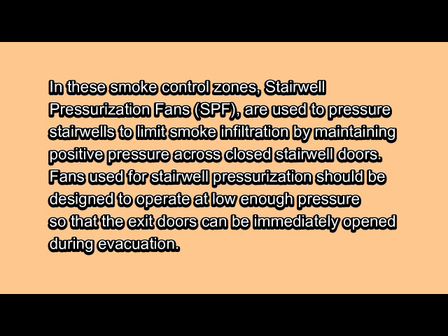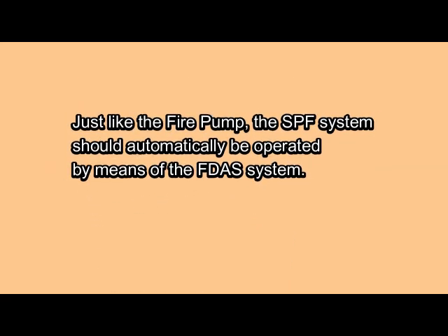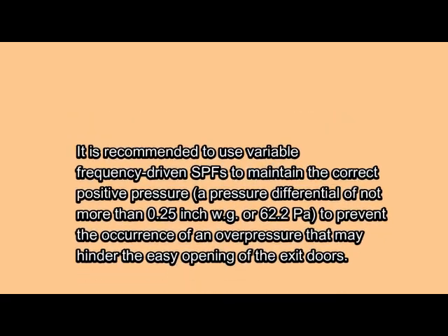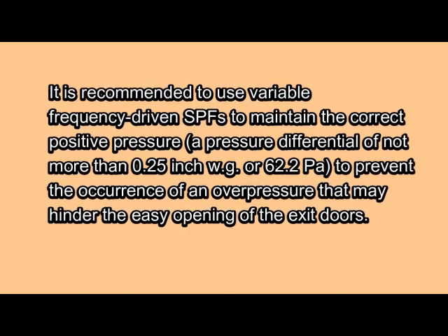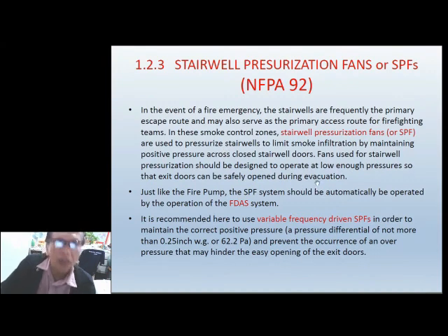Fans used for stairwell pressurization should be designed to operate at low enough pressure so that the exit doors can be immediately opened during evacuation. Just like the fire pump, the SPF system should automatically be operated by means of the FDAS system. It is recommended to use variable frequency-driven SPFs to maintain the correct positive pressure, a pressure differential of not more than 0.25 inch Wg or 62.2 pascals, to prevent the occurrence of an overpressure that may hinder the easy opening of the exit doors. So yan yung discussion ko dyan sa stairwell pressurization.